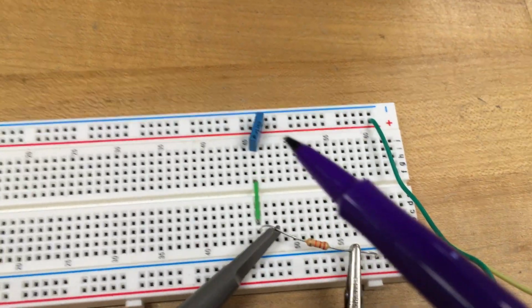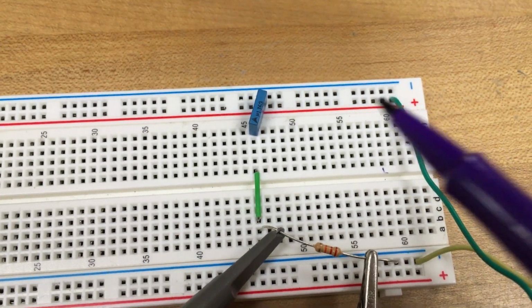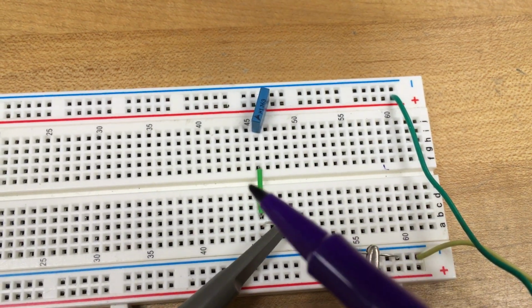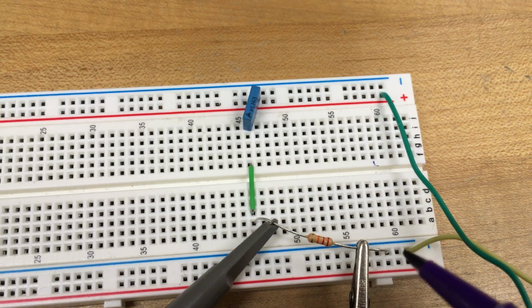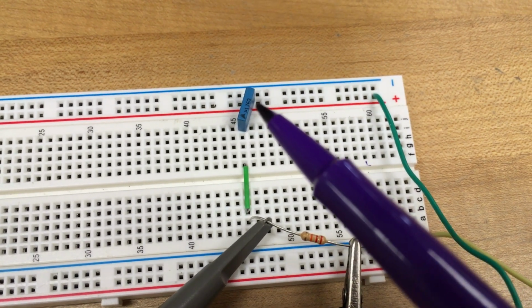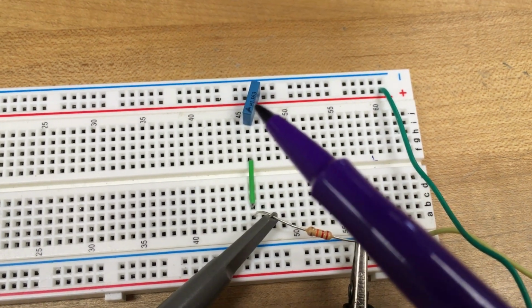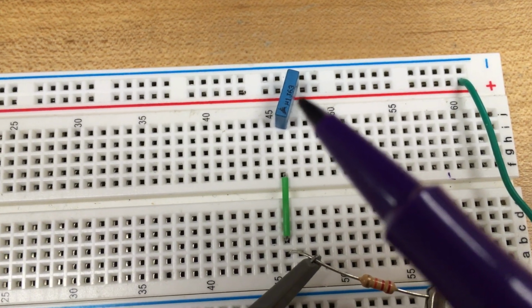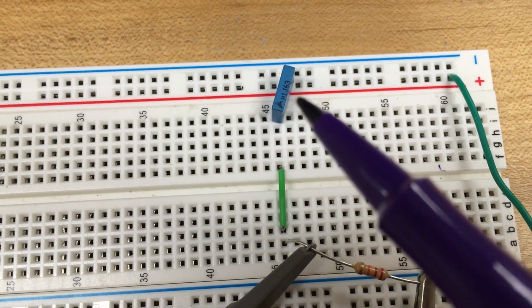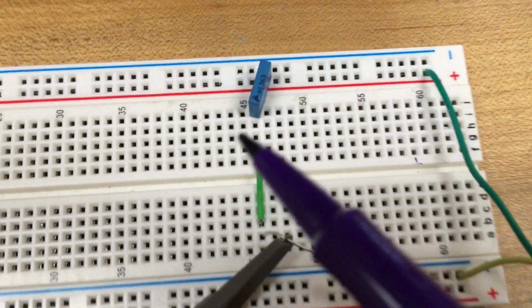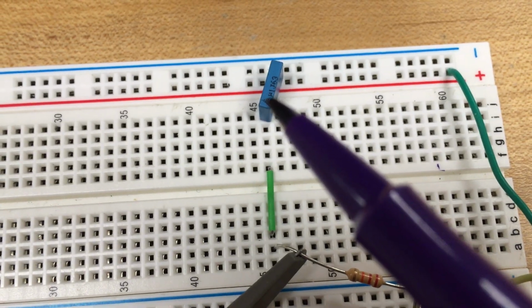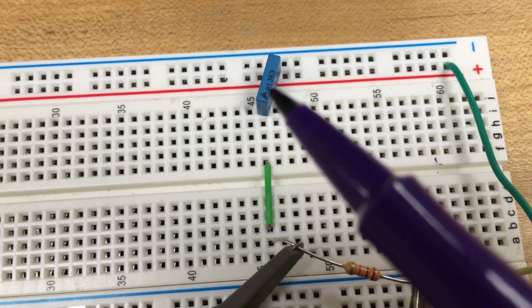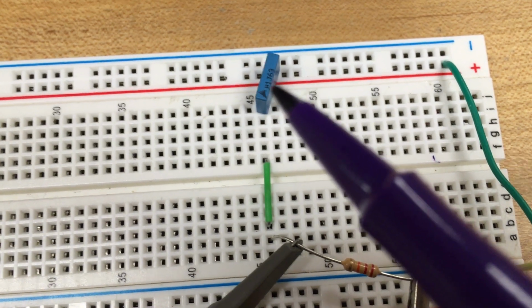And then the other item we have in here, so there's our circuit, comes through this thing, goes across here, comes across the resistor, goes back out. You've got a capacitor. You can see really tiny lettering on there. It says micro 1J63. Honestly, the only thing we need to pay attention to in terms of the marking is the micro 1. That's 0.1 microfarads is what that translates to.